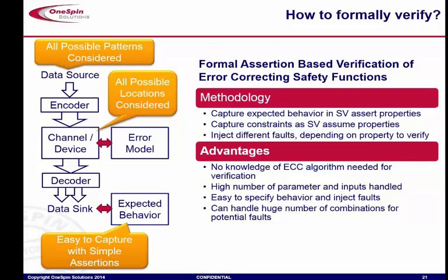And if in any way this can go wrong, so if there's any particular data and any particular 2 faults such that the error flag is not raised, formal will find them and just show them to you in the simulation trace. And if these things do not exist, well, formal can give you a proof that this mechanism works. So all 2-bit errors are actually detected. That's the big advantage that you have with formal verification over a simulation approach.